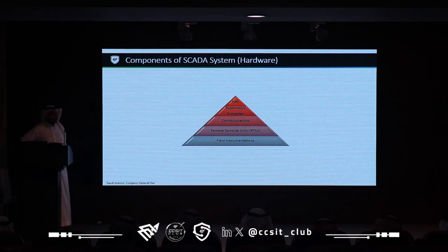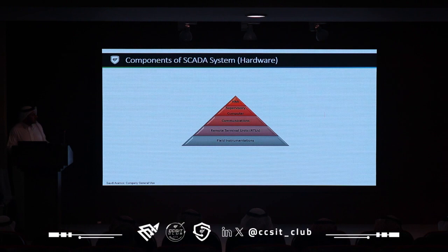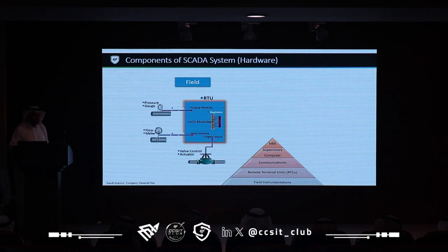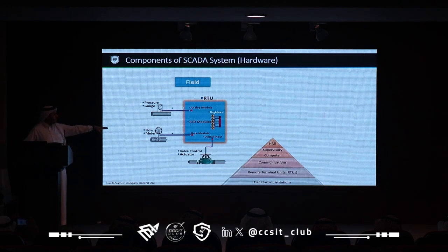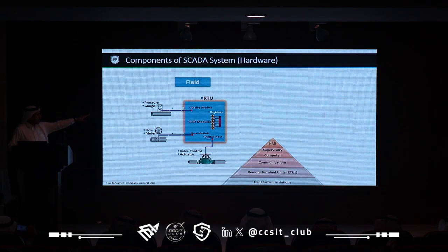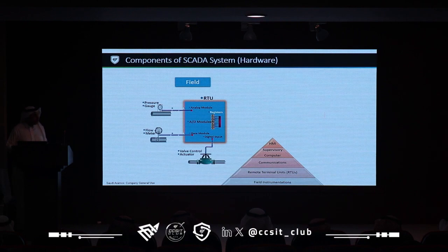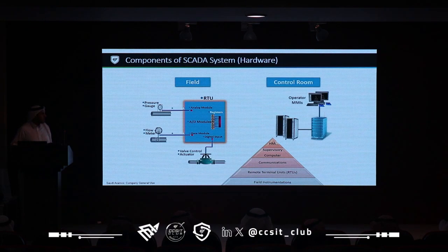Visualization, reporting, everything. And we'll give you details here. If you look, we'll start with the field devices. We have sensors in the equipment, such as pressure gauges and flow meters, connected to a PLC, or one type of PLC, the RTUs, that will read the instrumentation or sensors and process it, with registers linked one to one. And it will have another control room in a different place.